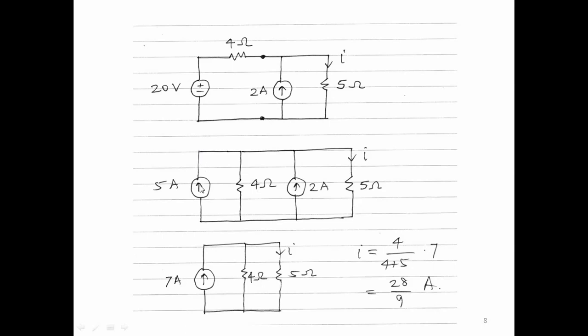So if this is plus minus like this, then the direction of the current source must be such that the voltage across these two nodes due to this current source and this resistance will be the same as the voltage polarity across these two terminals. Alright, so one has to be careful. If you put the wrong polarity, you will get all incorrect answers. Okay, so we have 20 volt 4 ohm replaced by 5 amps and 4 ohms.